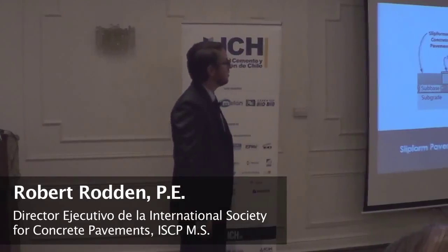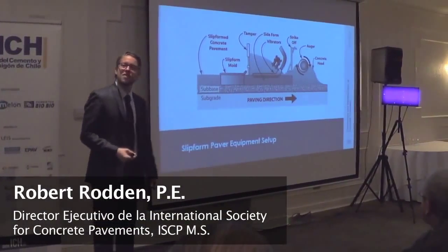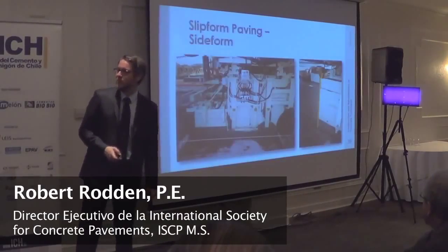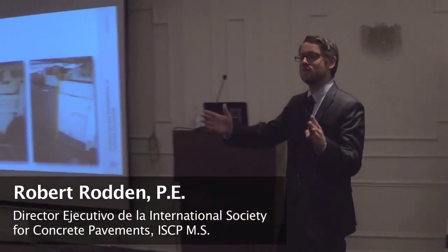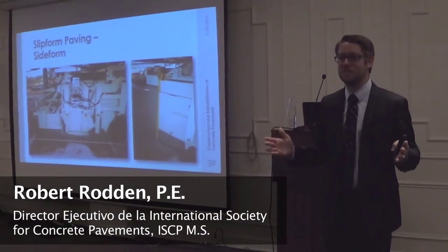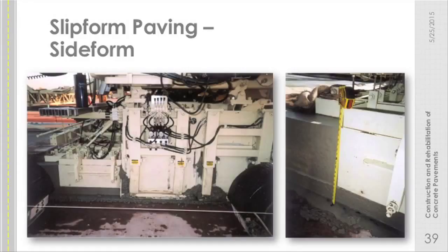side forms themselves. But we next have the side forms and the vibrators, which work together. They're both necessary at that one point. Side forms just contain the concrete. Because when the vibrators go, when those are vibrating, the concrete becomes a fluid temporarily. So all these are doing is preventing that fluid from just spilling out the sides. So they're relatively rigid and strongly reinforced.